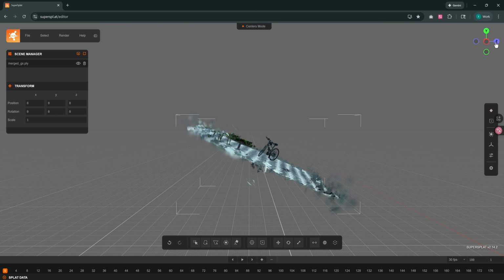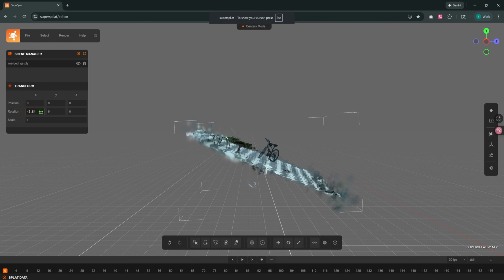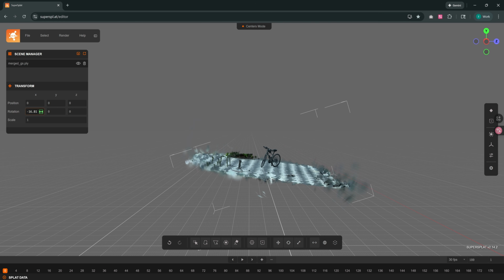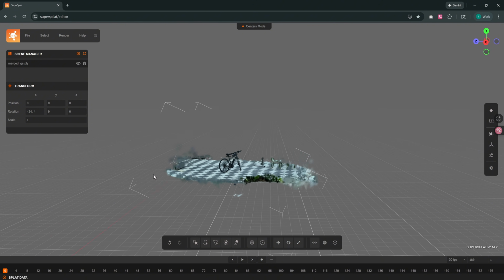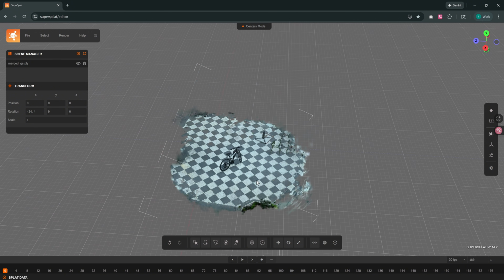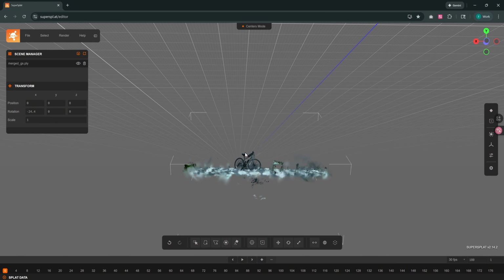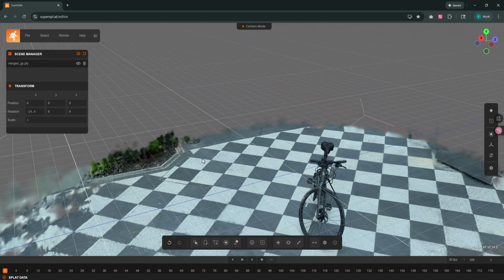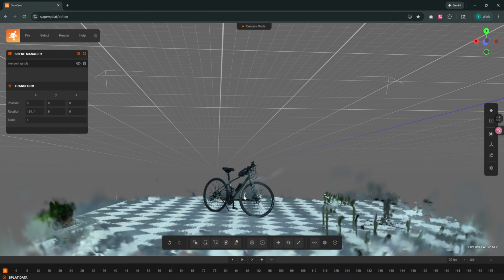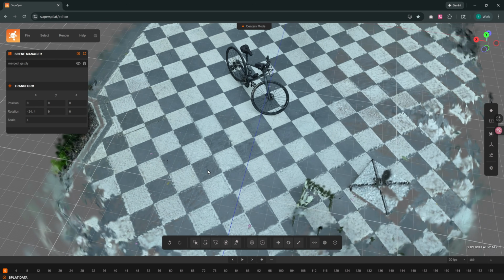You do not need to know the specific angle. Click in the input box for the x-axis on the left and drag left or right until the model looks straight, then release the mouse. After adjusting the coordinate system, the rotation operation is much smoother. Left-click to rotate, right-click to drag, and use the scroll wheel to zoom in and out. You can view the model from all angles.